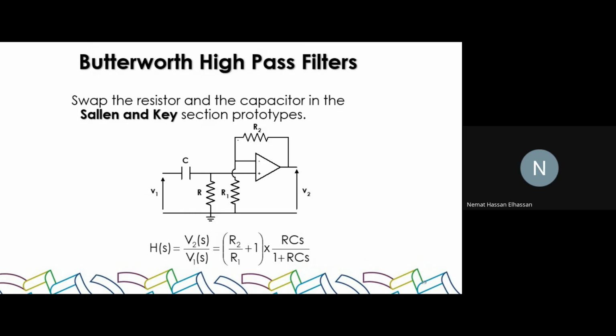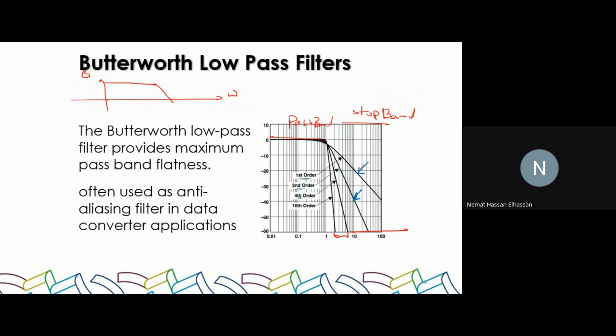So we are doing reverse engineering. Instead of starting with the circuit design, we start with what type of transfer function we need. For example, in applications where we don't care about a sharp transition but we want a steady gain, I could take a first or second order filter based on the components that I have.